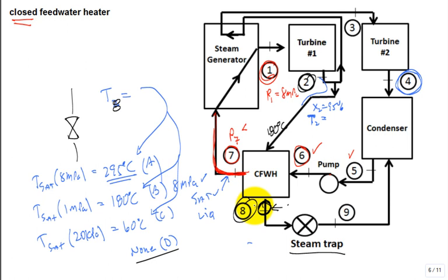So let me ask you this. The hot fluid comes in at 180 and the hot fluid leaves at 180, and the cold fluid comes in probably around 60 degrees C, a little bit over. Remember, it's like a half a degree above 60 because it's coming out at 60 degrees C right here. All right, even the most clever engineer, do you think I can design a heat exchanger that's going to bring out 295 degrees C?